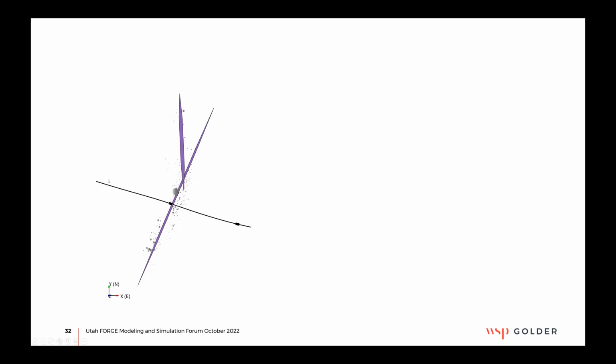That being said, it was something we were looking for. So we had the 4 sets that we considered more the pre-existing natural fractures. And in addition to that, we were looking for this new orientation based on the current stress model. So we were looking for 5 different orientations, the 4 existing ones plus this new one. And the fluids that were used during the stimulations were different. I believe slick water was used for the first 2 zones, and a high viscosity fluid for the 3rd stage. And we did see a very different response, I believe,